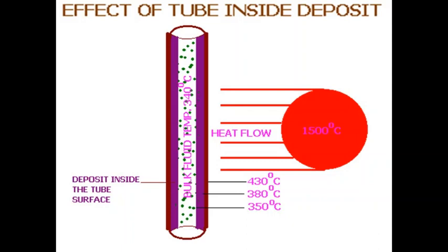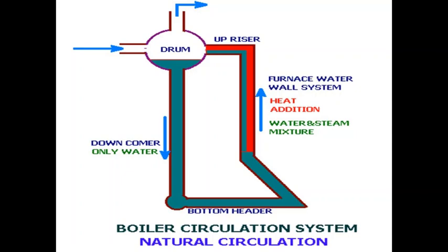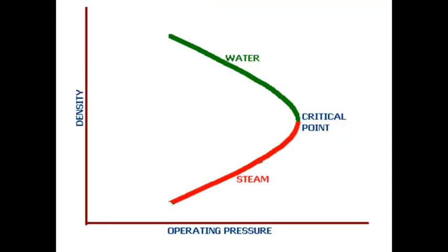Consequently, natural circulations occur due to thermosiphonic action, driven by gravity, and as the density difference between the downcomer column of water and the water steam mixture within the water walls creates the thermal head, that moves and circulates this total system, water steam mixture and water, so that the movement continues.